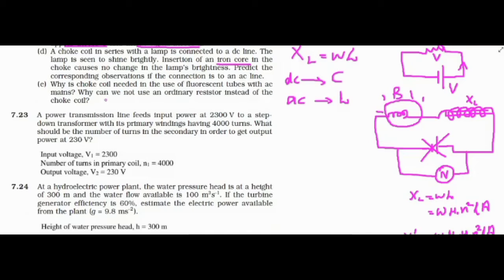You can see we have a starter there. By a momentary short circuit, this starter will produce a high current which can be converted into high voltage with the help of choke coil. Okay, because a sudden variation in current will produce a very high induced EMF, and that high induced EMF can be considered as a high voltage which is capable of producing electric discharge inside the tube.